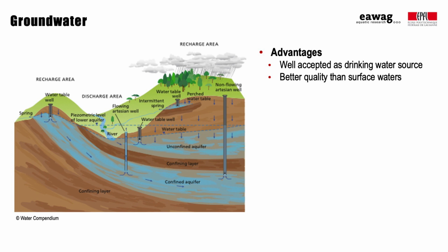Groundwater quality depends strongly on several factors like geological conditions, adequacy and type of extraction technology, depth of aquifer, and any existing protection measures. Deep aquifers are less vulnerable to contamination than shallow aquifers near their surface, which are likely to be influenced by contaminated surface water bodies, on-site sanitation systems, landfill discharges, industrial chemicals, and other anthropogenic pollutants.